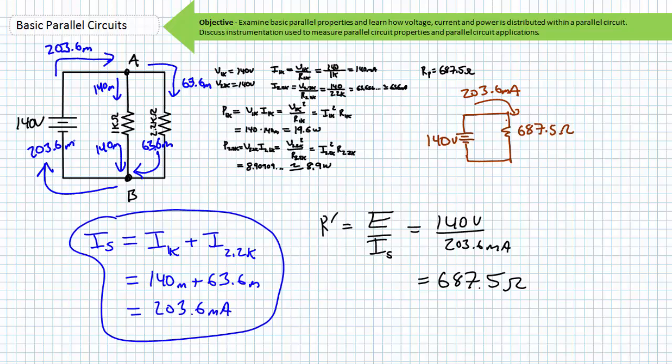However, you'll be happy to know it really doesn't get more difficult than this. What goes in must come out. What goes out must have come in. Not only does Kirchhoff's current law aid in circuit analysis, it is also a useful sanity check in that current coming out of a node can never exceed that coming into it, nor can current entering a node not leave it. The sum of current inputs always equals the sum of current outputs.